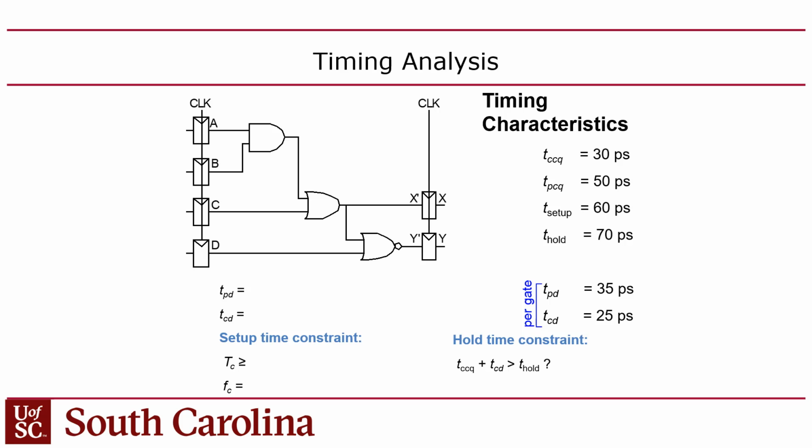And by the way, this could also be the case where the outputs of your logic wrap around to these ABCD registers. You could have this in a loop too. It doesn't matter. The point is that anytime you have outputs of flip-flops driving logic that eventually drives inputs, and we're all in the same clock domain, then you have to make sure that they obey the dynamic discipline, meaning that you obey the setup and hold time, right?